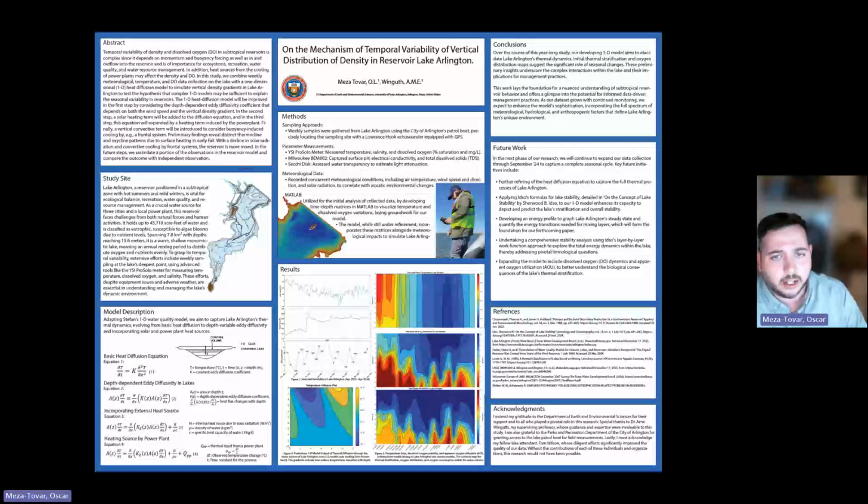With that, we did use the YSI Pro meter, which helped me figure out temperature, salinity, dissolved oxygen saturation, and concentration at different depths. My Milwaukee BEM 802 captured surface pH, electroconductivity, and total dissolved solids. Lastly, I used the Secchi disc, which helped me assess the water transparency and to estimate light attenuation in Lake Arlington, each time I went out.